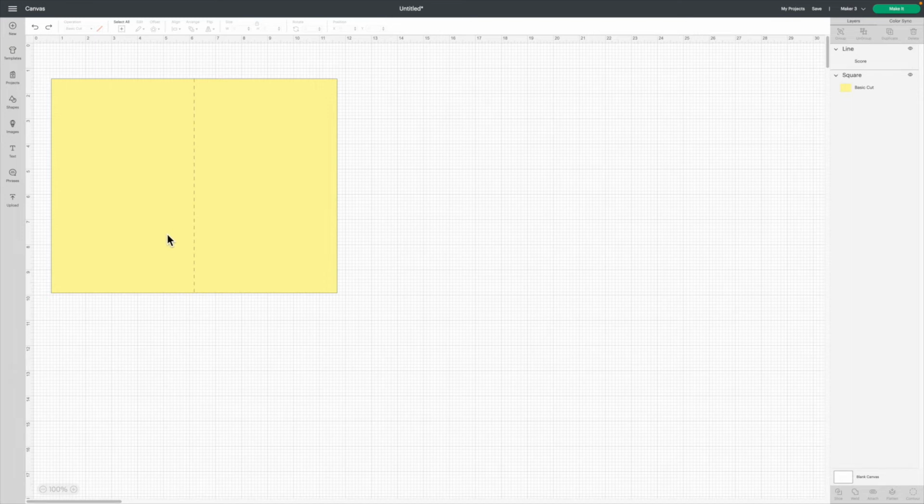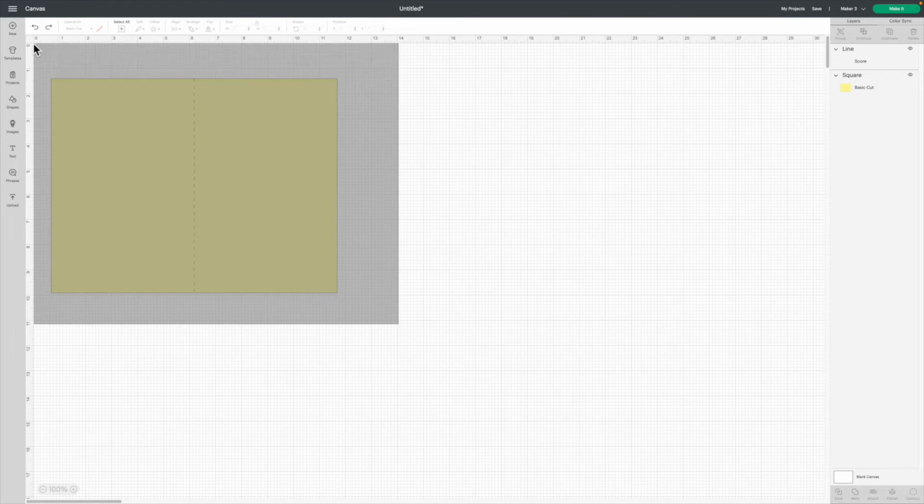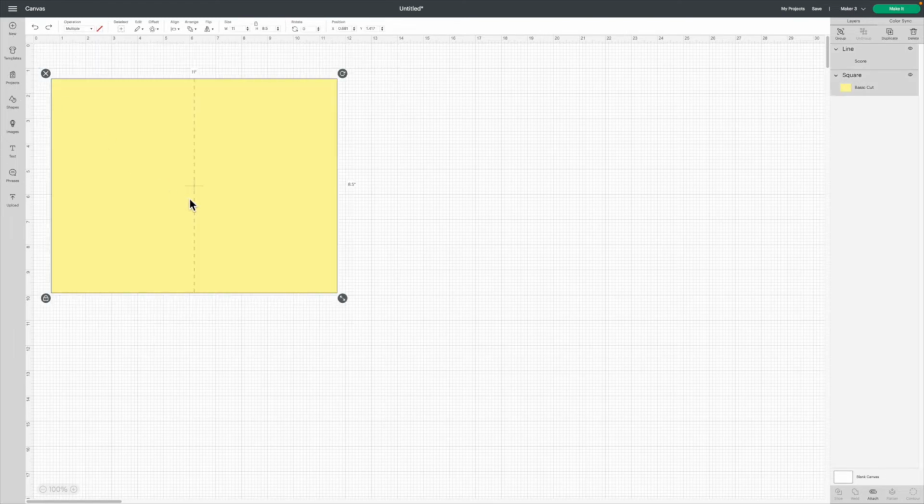We want to make sure that this score line and the cards stay together in this position since we went to all the trouble of aligning it. To do this, let's attach these two. Make sure both objects are selected, again dragging over them or making sure they're both in the gray over here. They'll have the dark gray background on the layer sidebar if they are selected.